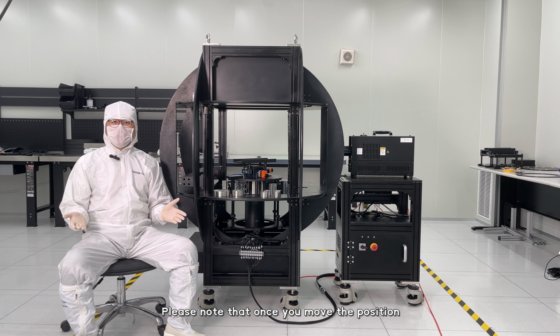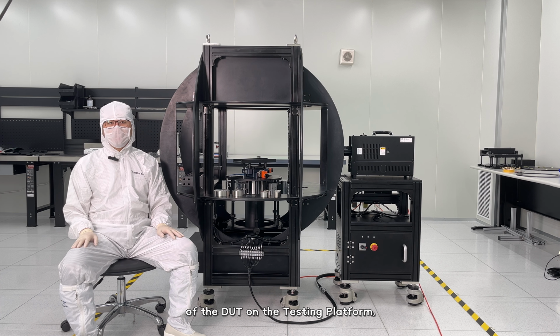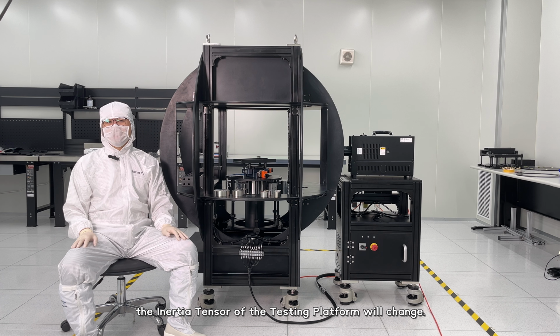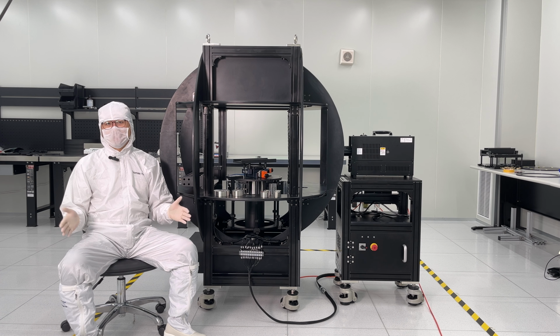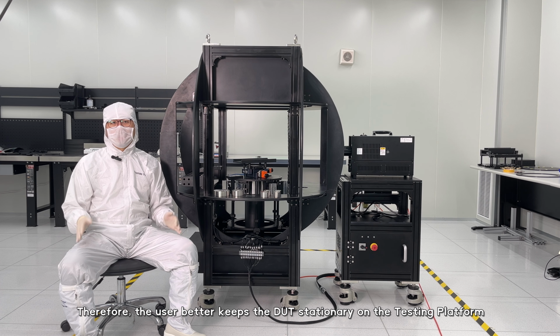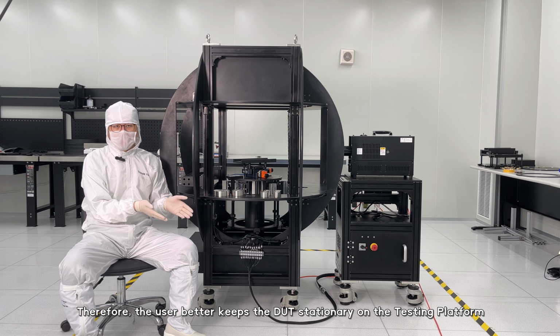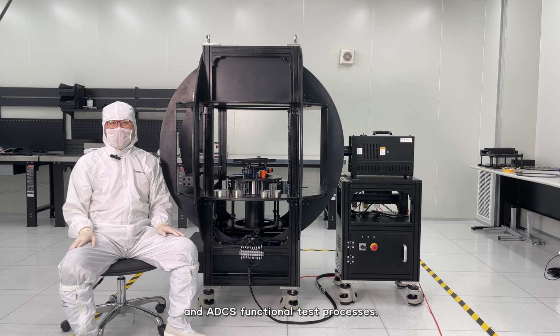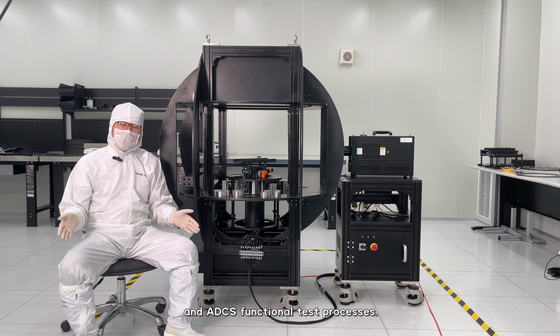Please note that once you move the position of the DUT on the testing platform, the inertia tensor of the testing platform will change. Therefore, the user had better keep the DUT stationary on the testing platform for the entire mass properties measurement process and the ADCS functional test processes.